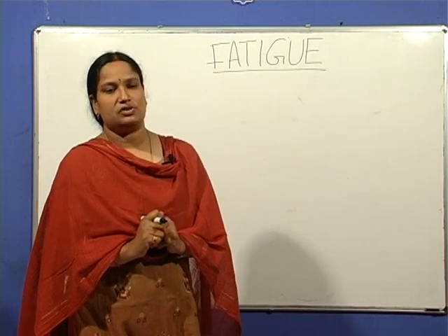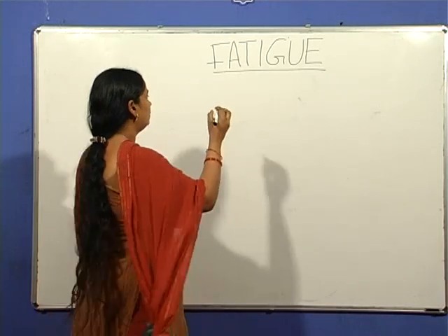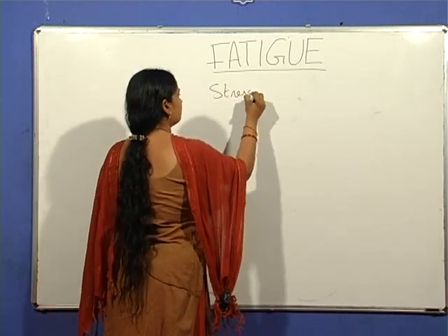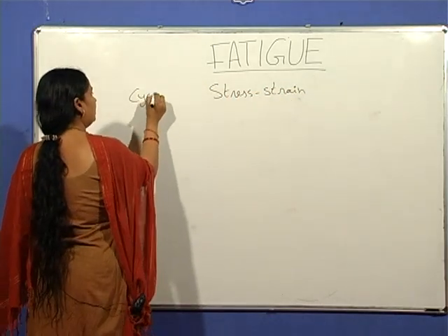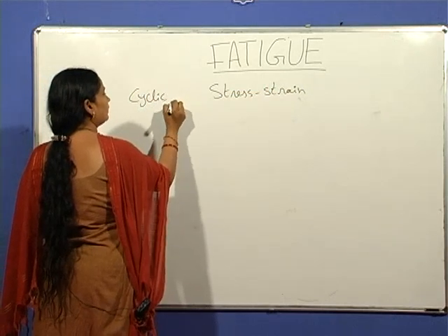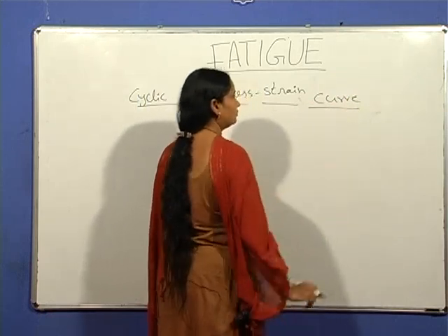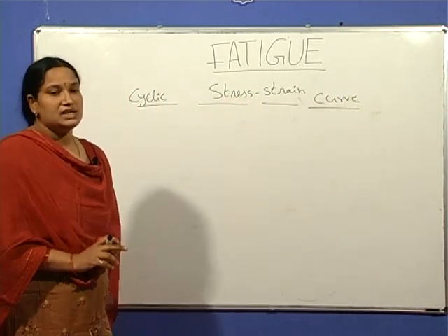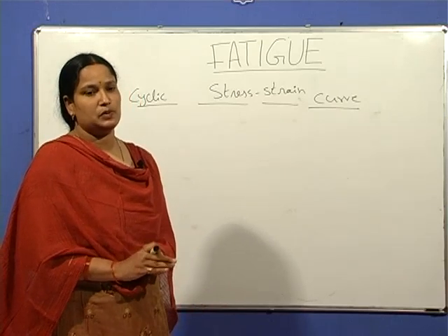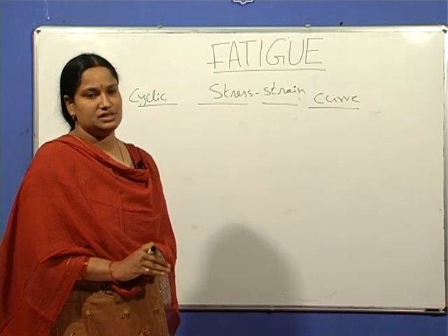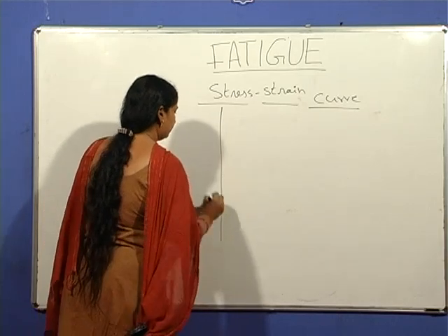Now we see the stress strain behavior of a material during cyclic loading. Cyclic stress strain curve. Plastic deformation is not completely reversible, so the stress strain response of a material is complex during cyclic loading. Consider a material